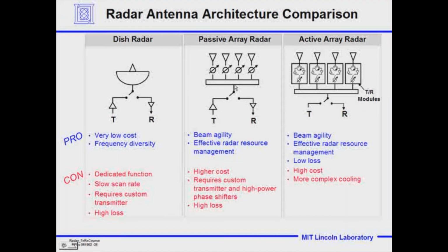a set of waveguides that would branch out to different places and feed, like the trunk of a tree. They might have one transmitter taking care of one quadrant of a phased array, another transmitter taking care of another quadrant, and then the waveguide would branch out with a 3-to-1 feed, and then another 4-to-1 feed, another 4-to-1 feed, like the branches of a tree, so that microwave energy would finally get to the phase shifters, and then the phases would be changed and the energy radiated, to generate the beams on transmit or receive.